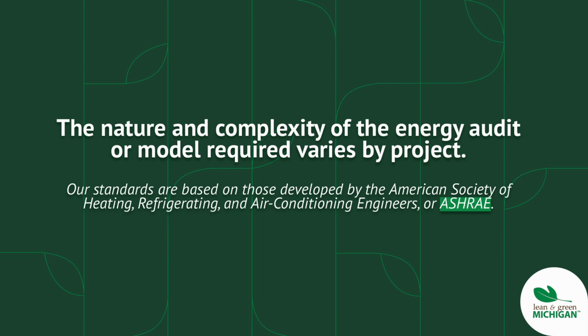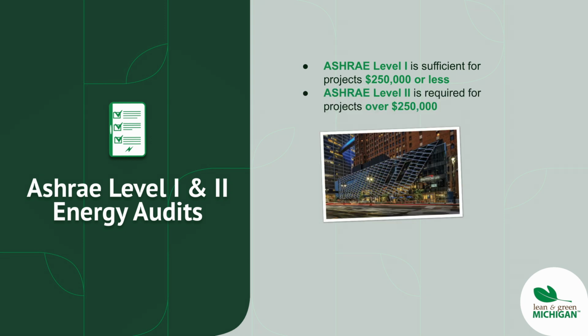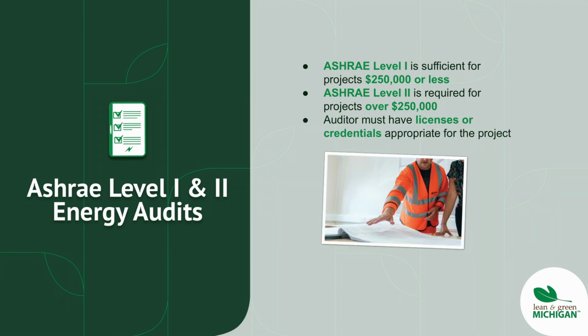We have based our audit standards on those developed by the American Society of Heating, Refrigerating, and Air Conditioning Engineers, or ASHRAE. For PACE energy projects that have a total assessment value of $250,000 or less, Lean & Green Michigan requires the submission of an ASHRAE Level 1 audit report. PACE energy projects that are over $250,000 require an ASHRAE Level 2 energy audit. The auditor must have licenses or credentials appropriate for the project at hand, certified energy manager, engineer, etc.